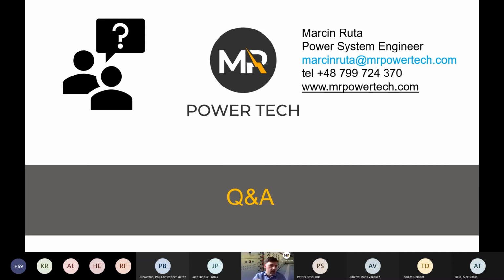So if you model UPS and your batteries are connected to the common DC bus bar, so you have multiple panels connected to the DC bus bar, it very much depends what kind of protection you have in the battery panels, or if there is protection at all. So you might expect that on the main bus bar it will be worse. But in practice, the worst situation is on the panel itself, on the battery panel. So the simple answer is, if you can run separate connections to each UPS module, this will be better from an arc flash point of view. But in practice, you might improve it a bit with the protection settings on the DC side.